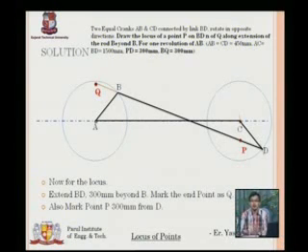So again, I will now follow the same procedure that I did back then. Now you'll ask, how will I follow the same procedure? In that, what happened? I divided the circle into 12 parts. Here also I'll do the same. But there is one single difference. As there was a difference between the simple slider crank mechanism and the offset slider crank mechanism, there is a little bit of difference between the offset or simple slider crank mechanism and this particular 4-bar link mechanism. What will I do? Now I will divide the circle into 12 parts. The driven circle, the driving circle. This is the circle which I will divide into 12 parts.